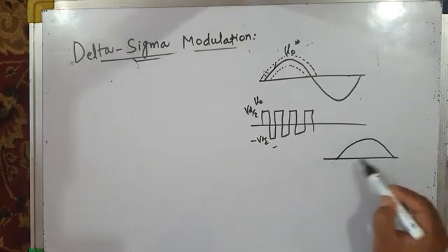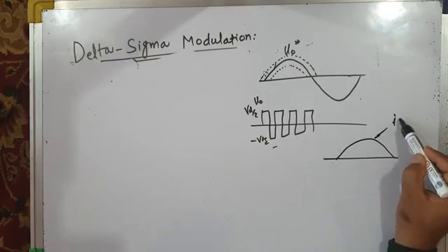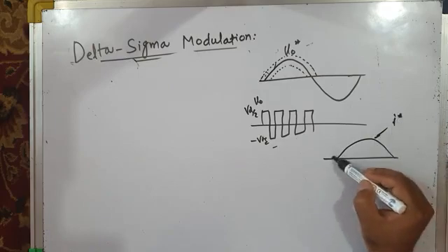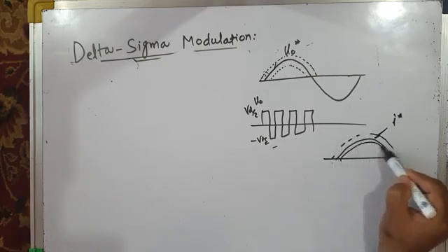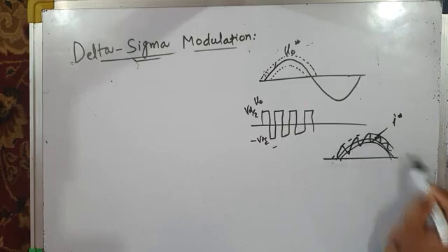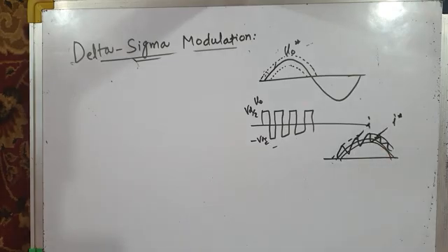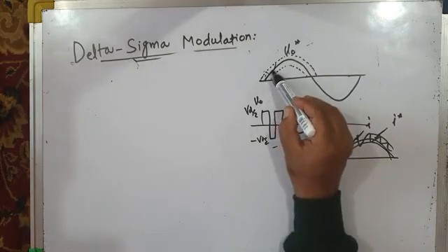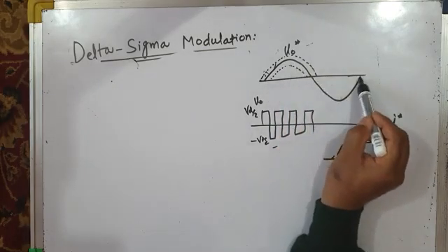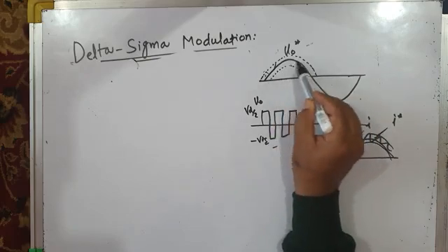There, instead of controlling the load voltage, you are controlling the load current. This was your reference load current, this was the hysteresis band, and within this hysteresis band you are controlling the load current I. Is it possible to do that in the case of voltage? The answer to this question is no, absolutely no, we cannot do that. The reason being, your reference load voltage V0 star is continuously varying, you can see, sinusoidally varying.